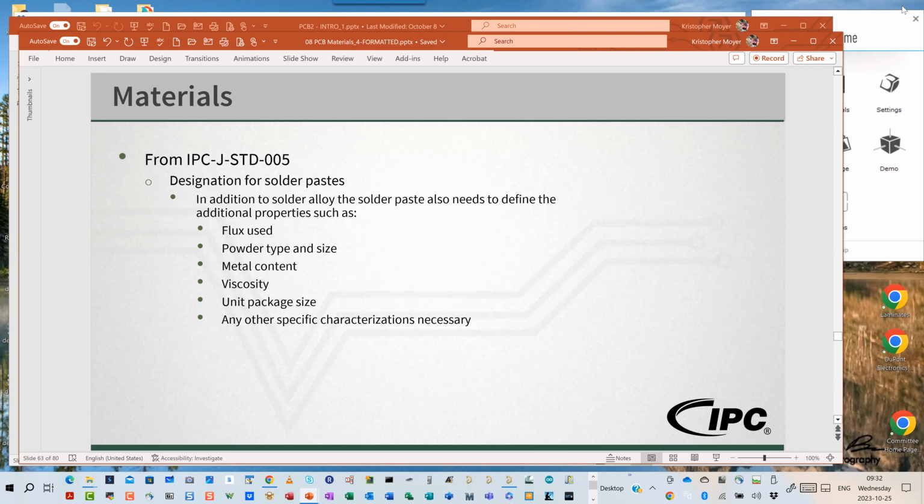Yes, the way wave solder machines work, if you ever watch a video of one, the very first stage is the board coming in. They literally have a mister spraying the entire surface of the board with flux. Then you go through the molten wave of solder, and the flux helps the solder wick up through the holes because it's traditionally meant for through hole. Then when you get out, you absolutely have to go through wash because the entire board's sticky with flux. Okay. Thank you. I'm going to bring that up to the uppers. Thanks. No problem. Make my life a little easier.